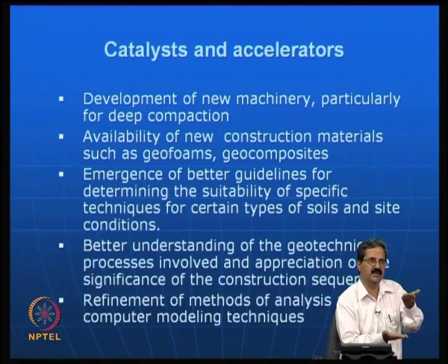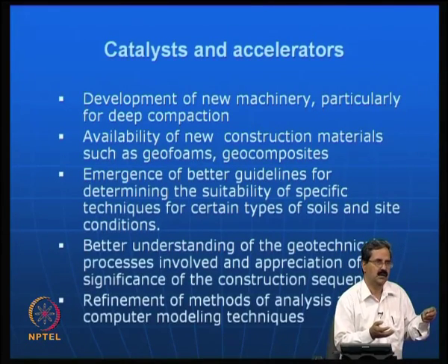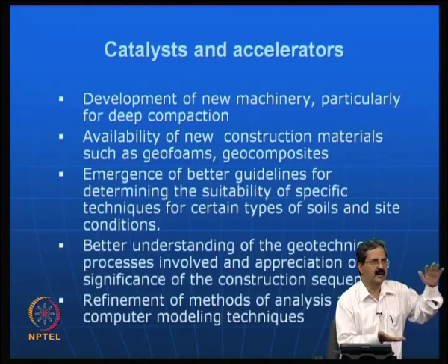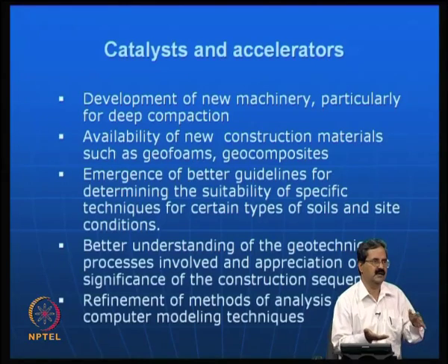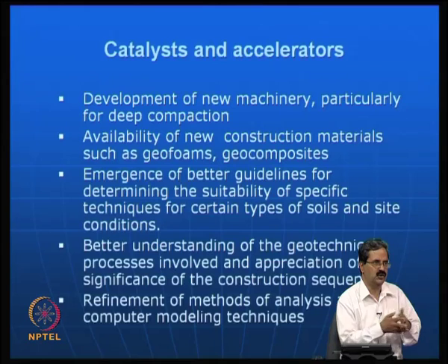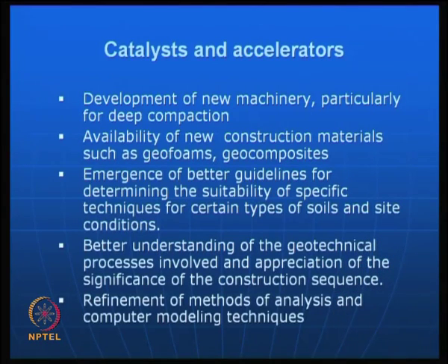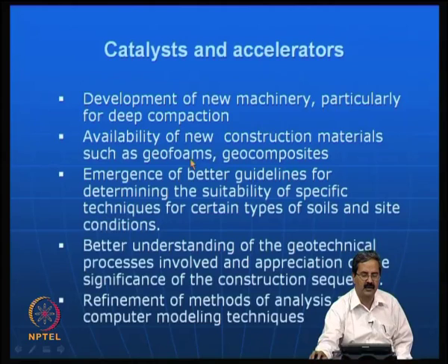That is the principle, that is why you have so many layers. Why? Because you would like to distribute the load so that the subgrade is affected to the minimum extent. But when you have a material like geofoam, which is not really compressible, you just bring it in a truck, place it there, put some wearing course, and merge everything. It is fine for us. So, you can construct roads very fast. Geofoam is one. There are many actually, particularly in road construction, there are so many things that contractors should be ready to absorb as techniques.